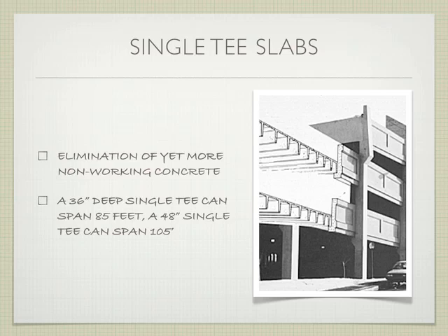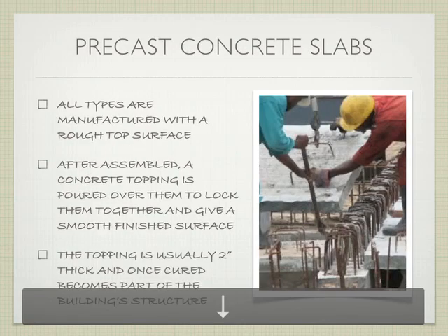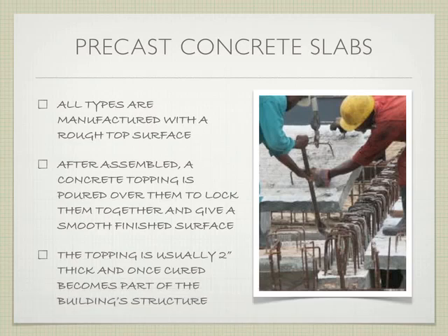You're allowed to do 110, but you've got to have the wide load people and the pilot cars at the front and the back and all that kind of stuff. So think about the challenges of getting something like that to the site. So yeah, it's really great that you can get the spanning distance, but you also have to weigh in how do you get it to the site. And so that's the disadvantage that's important to talk about, okay?